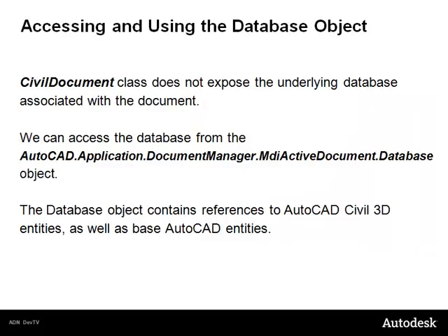The CivilDocument class does not expose the underlying database associated with the document. However, you can access the database from the AutoCAD Application.DocumentManager.MdiActiveDocument.Database object. The database object contains references to Civil 3D entities as well as the base AutoCAD entities.